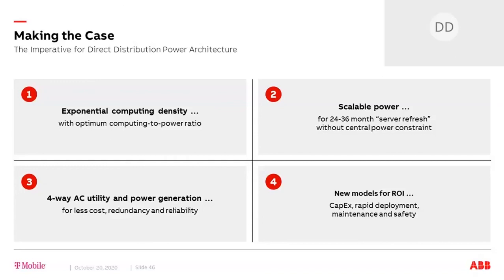AC power sources. Our long runtime battery plants provide a good reliability for decades. But both internal and external data indicate that we will achieve substantially higher reliability using the 2N utility and 2N generator model. Our goal was to exceed an MTBF greater than 20 years for the entire portfolio, and we have done that.